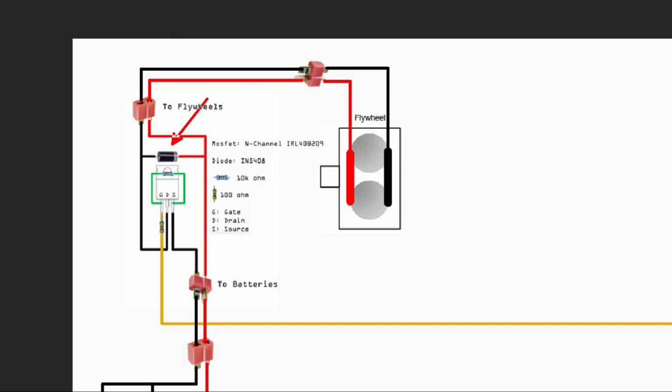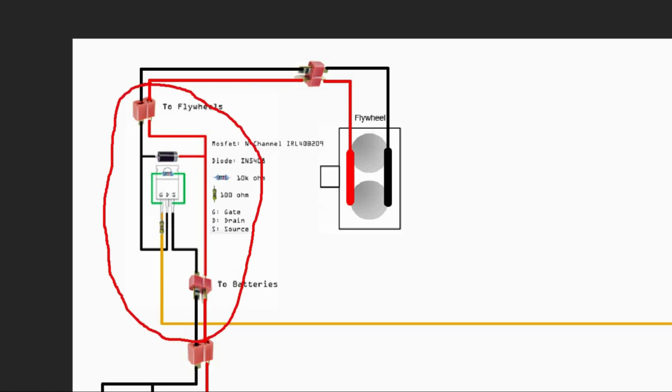Okay, so over here, this is the diode. This is the flyback diode. When the flywheel is not running, it's still spinning, so it's going to produce some residual power, so you want to channel it back and let it just wind down. So you can connect it across here if you want to. Sometimes I do that. If you do that, the advantage is, of course, this entire setup itself is a separated unit. You can actually remove it as a unit itself.